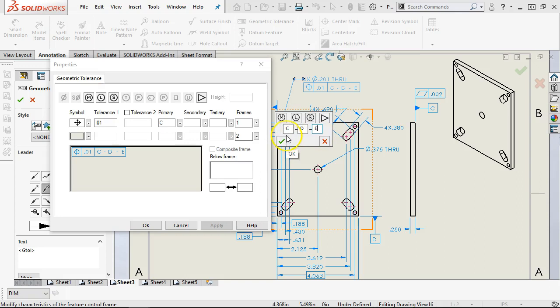And then the question is to have any kind of the bonus tolerance, which is a whole other conversation, but basically as the hole shrinks to its minimum value and or grows to its maximum value, how much can that tolerance envelope shift to accommodate the variation in size? Right, so if we go to regardless of feature size, it's just going to look like, and I'm not sure about that one, I have to check into that. Oh, this was a combined. All right, so I got ahead of myself on that one.